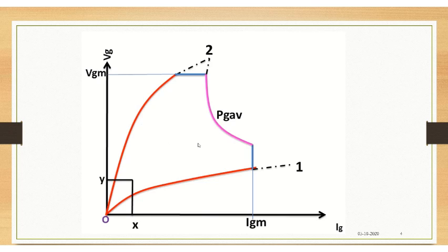So care should be taken, looking at the SCR you have chosen and its specifications mentioned by the manufacturer, to design your circuit in such a way that even if you have noise or any unwanted signal with some minimum voltage, it will not turn on the device.